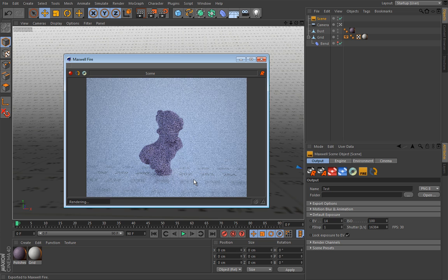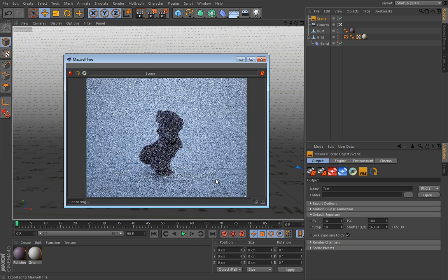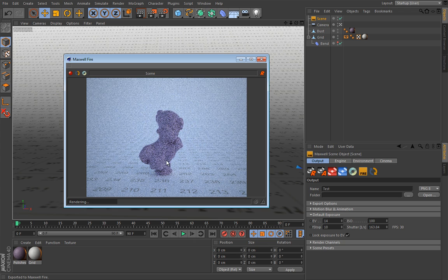we will give it a second or two. You can clearly see now the effect of depth of field. Our object is in focus, but only a tiny portion is visible, and we can clearly read out those numbers. Now, when f-stop is low, then the depth of field is narrow. On the contrary, if you increase this to, let's say, 10, let's refresh that, that same depth of field will become wider. So lower means narrow, higher means wider depth of field.